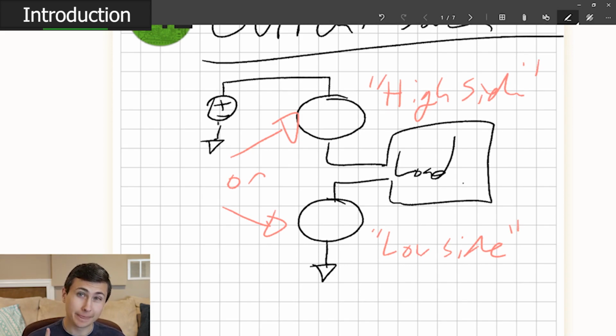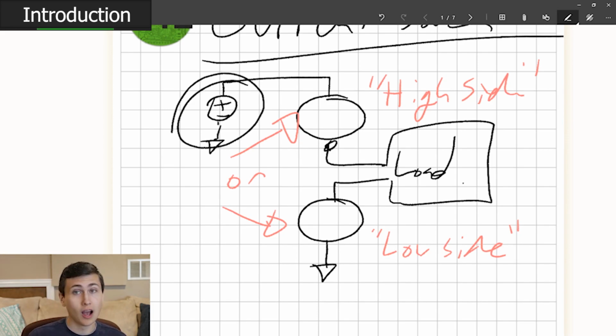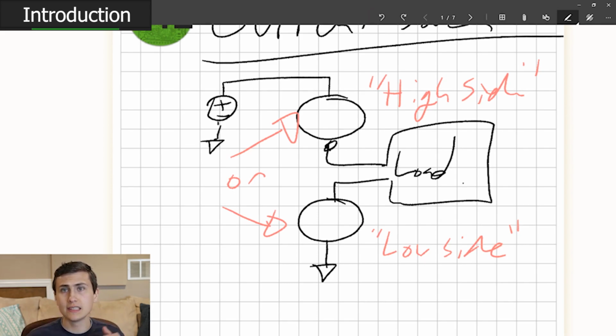Okay, what does this mean? Well, typically, I would prefer a high side regulator. You might be thinking to yourself, why? That sounds pretty complex. We need to do current sensing up here. We need to do all kinds of stuff up there. That seems kind of complex. And, well, let's say this were 100 volts, 200 volts. That can be kind of complex when you've got this control loop kind of touching something that's at a few hundred volts DC. So there's some complexity with needing to add this DC offset to a bunch of control circuits.